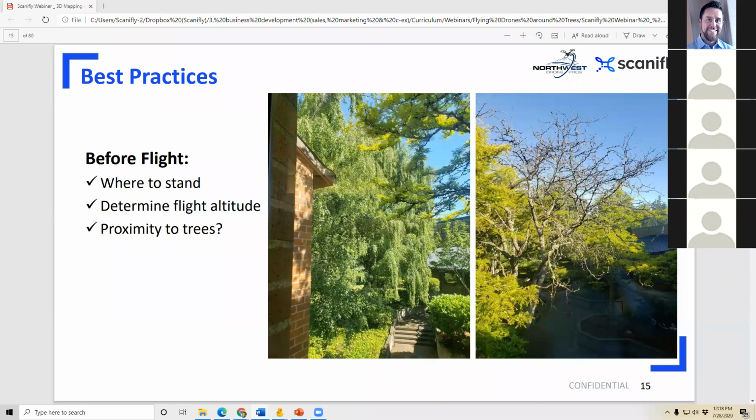Generally, you'll be flying 2 flight paths, which John's going to be discussing later, a detail and a context. The context flight is the higher altitude flight, and it's usually around 70 feet, unless, like in my circumstance, there are trees higher than that, which most likely there are here in the Pacific Northwest. And the detail flight is usually about 10 feet above the roof line. So you just want to map out your 2 flight plans in your head and know for the context flight that with the camera angle needed, the full point of interest in frame and 100+ foot trees, you're going to need a decent diameter flight path.